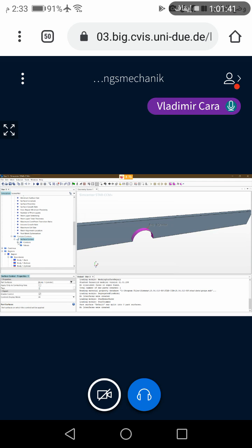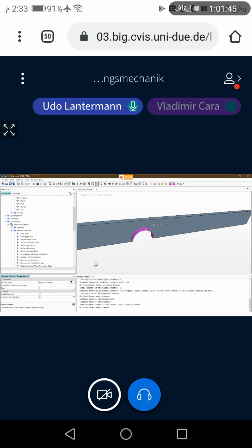I just cannot find this custom controls. This is in Operations, Automatic Mesh. Okay. I will close the default. And then there are three options: Meshes, Default Controls, and Custom Controls. So again, Custom Control, right mouse button, New, Surface. And then in Surface, choose the part surfaces cylinder.